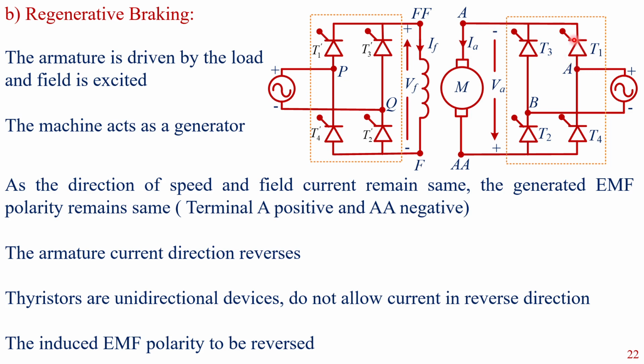As there is a full converter which will not allow current in the reverse direction, the induced EMF polarity can be reversed by reversing the field current.